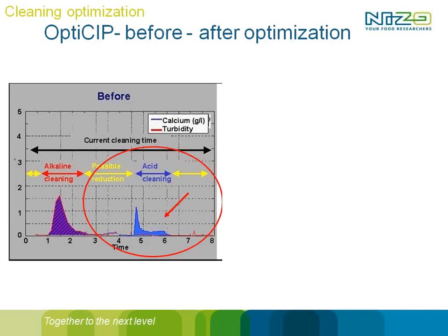What we do is actually we have a cleaning cycle, and during the cleaning cycle, each amount of time, for example each minute, we take a sample. And in the meanwhile, we're logging all relevant data. So what are the temperatures we're using, which valves are open, are we adding acid, caustic, or whatever, are we adding water, are there any other important features to be logged.